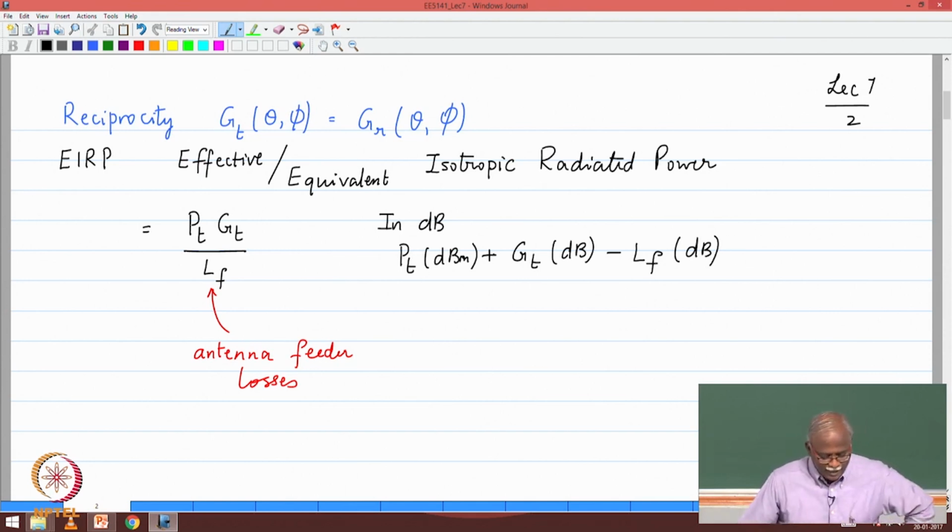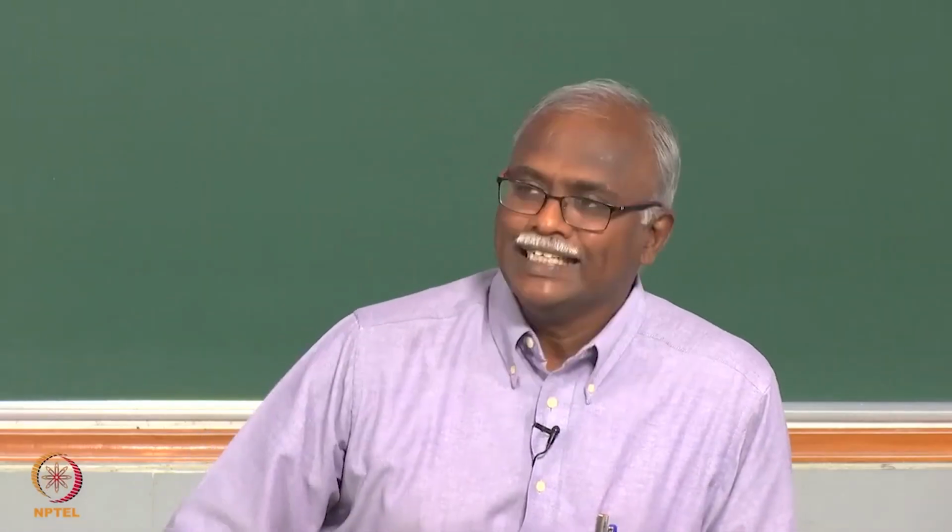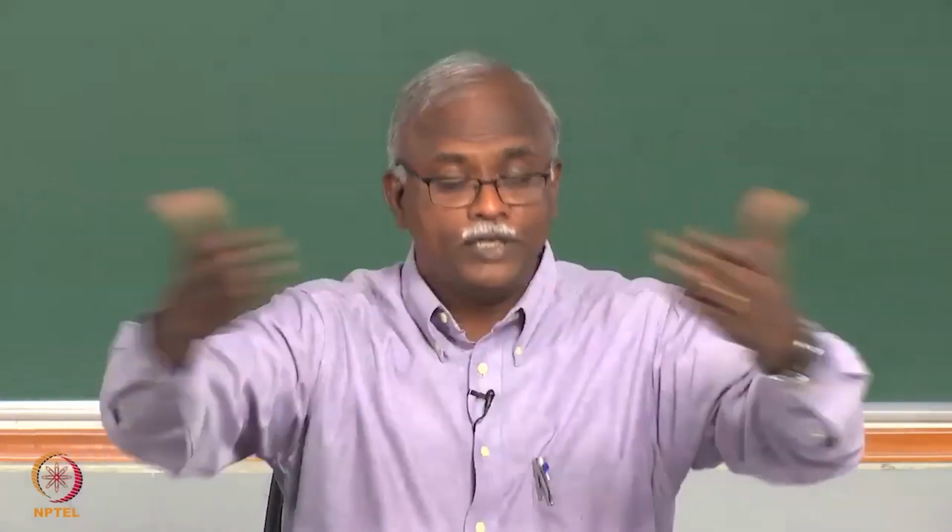Now there's another aspect that I would like you to be very familiar with and confident of using, because transmitted power is what comes out of your power amplifier. Now after the power amplifier, if you go back and look at the original diagrams of a base station, you will find that there is an antenna. The antenna typically gives you some gain. So that contributes to the effectiveness of the signal that you have transmitted. So PT times the gain of the antenna is actually what you will see going out into the air.